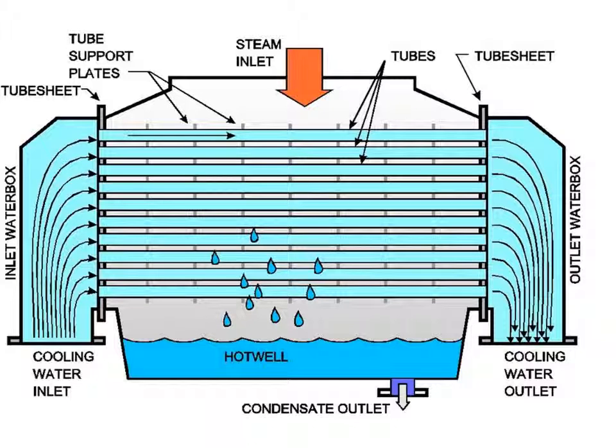After the steam has passed through the turbine, it is directed to the condenser. The condenser is another large heat exchanger. It takes steam from the secondary coolant channel and returns it to its liquid state using a third reservoir of water, typically a large river or lake. After being pumped through the condenser, the water from the tertiary reservoir is returned to the environment at a slightly higher temperature. The water in the secondary coolant channel is pumped from the condenser back to the steam generator, where it can continue to extract heat from the primary coolant channel.